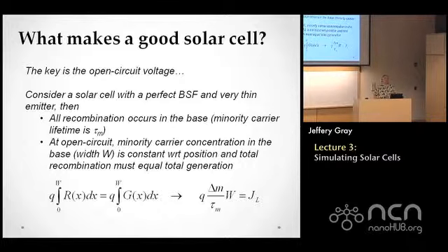And I think Professor Alam here, yeah, he's sitting there in the back, knows that from his organic solar cells. They probably have much better short circuit current than they do open circuit voltage. It's much easier to get the short circuit current, but at open circuit voltage, that's basically where all the warts show up. So, for a good solar cell, if you can get a good open circuit voltage, you probably have everything else handled in the device as well. It's not 100% sure, but a very good case for that.